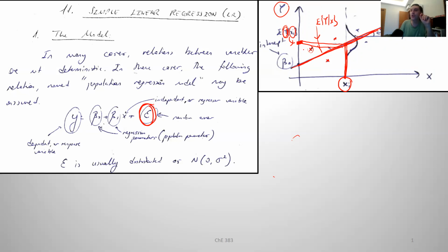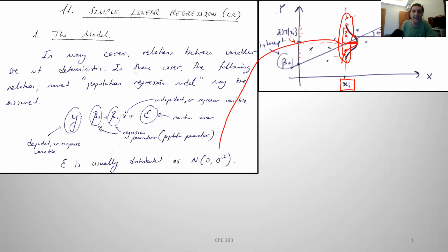Each time you observe a y value, the distillate composition, each time you sample at the same xi value, note that you are not going to be on this line. You are going to be here, along this vertical line, because you are running your process at that corresponding xi value. So we are going to be obtaining samples on these y values, but around this expected value. And note that the distribution of these samples will be normal, where the median or the mode or the expected value is here, just the peak, and this variance here is going to be exactly equal to that.